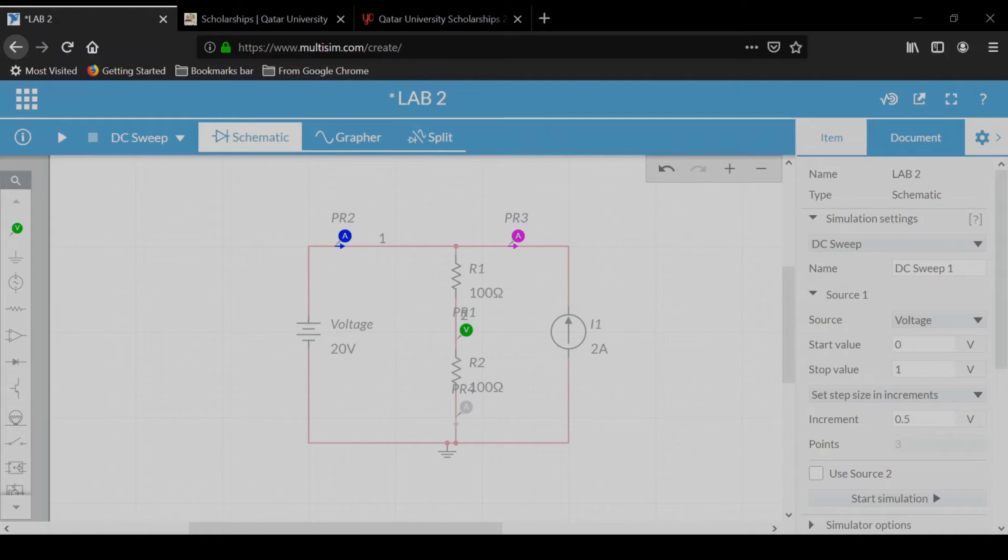The simulation then will run the circuit with the voltage source at -10V, taking all the measurements at this state. Then it will run again at -9V, then again at -8, all the way up to 10V, taking the measurements of every iteration of the voltage source. So the simulation basically sweeps through the voltages at the defined increment.